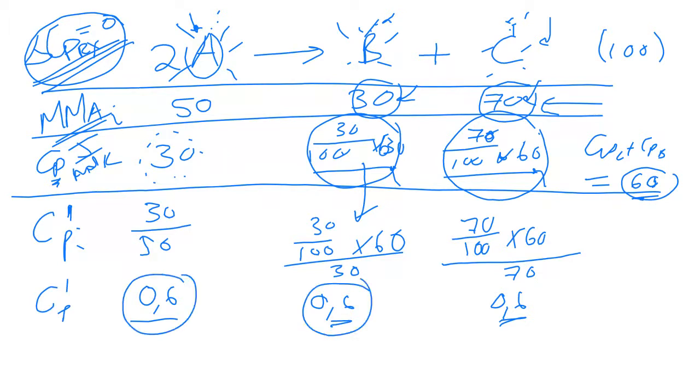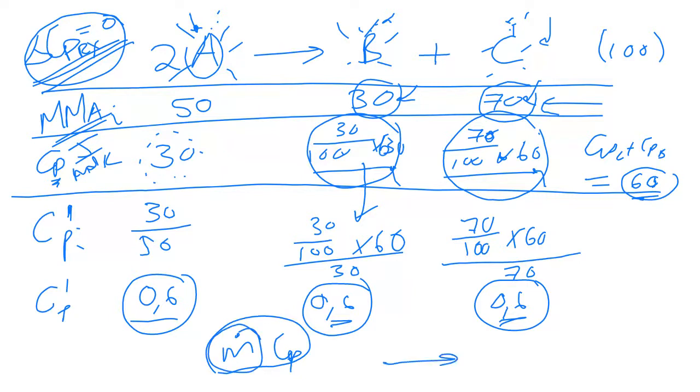This is what ends up happening over here. So the mass-based CP value of each of the components is then the same, and I don't change the MCP value. So MCP, if I want to heat up stuff, whether I'm heating up products or reactants, is going to be exactly the same, because the mass must stay the same, steady state. Mass as the reaction takes place must stay the same. And now I'm also proving that the CP value stays exactly the same. The mass-based CP value stays exactly the same.